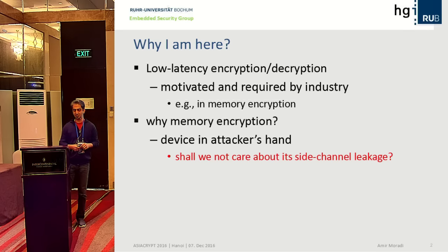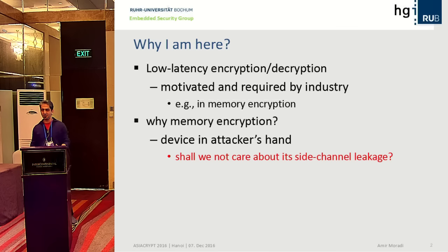But why is memory encryption required? Of course, in scenarios where the chip is in the hand of the attacker, because the attacker may be able to open the chip and read or dump the memory content. To protect against such an attacker, you go for memory encryption. Otherwise, in my point of view, there is no reason to have memory encryption, right?